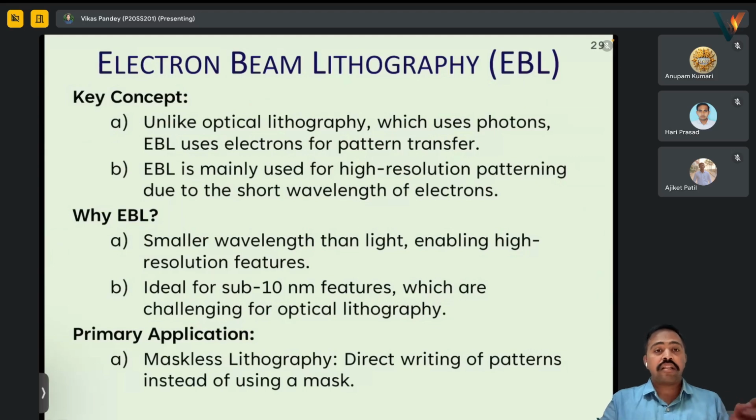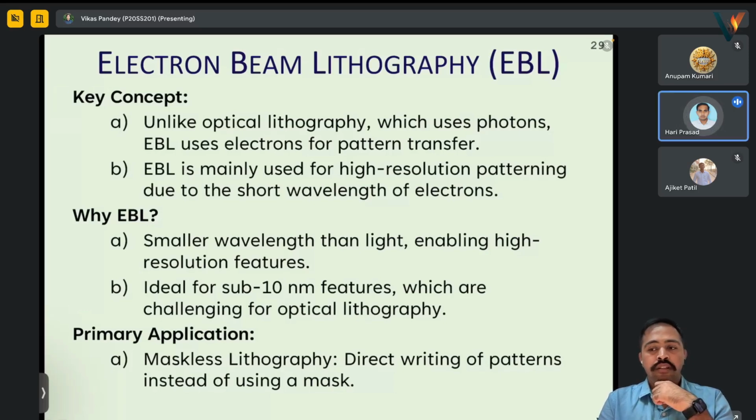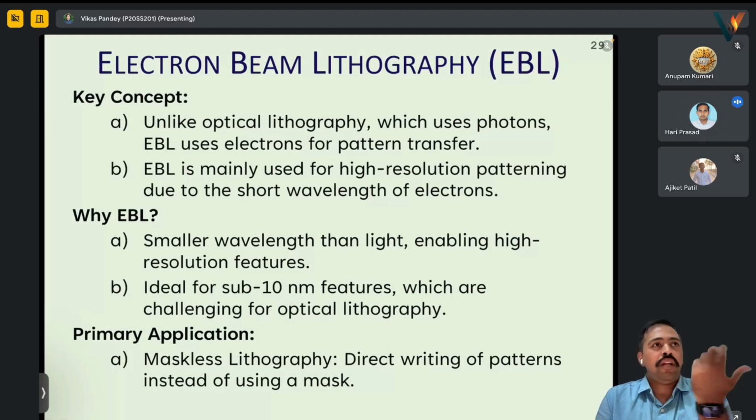So next comes when we are talking about resolution. Sir, one more. Mask will be normally prepared with chromium, sir. If you prepare with gold masks, what happens, sir? Why waste so much money over it? Because chromium works better, its work is just to stop light. And for gold, more thickness will be required to make a mask, because the reflectivity of a chromium mask is better than gold.